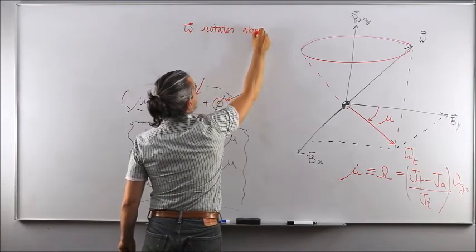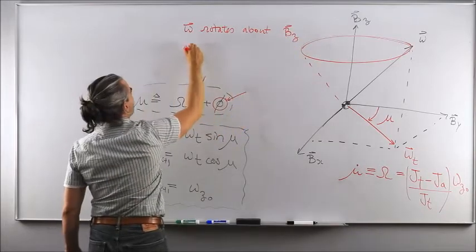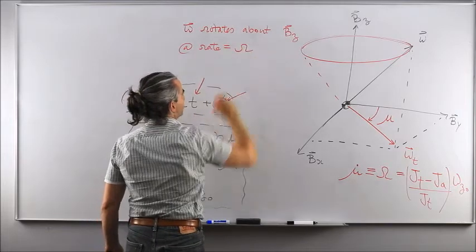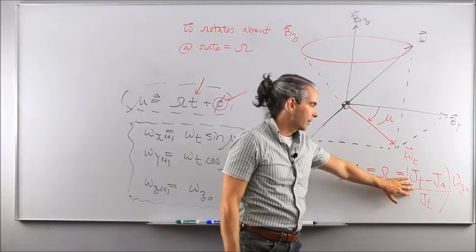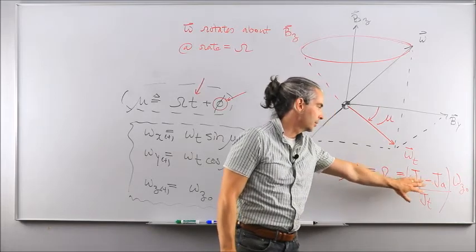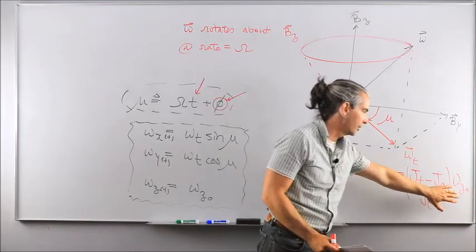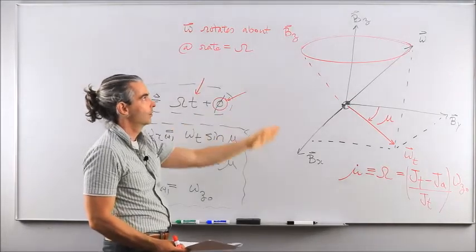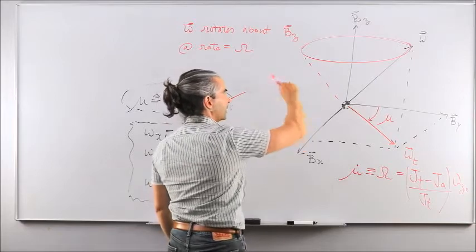rotates about bz at a rate equal to the relative spin rate. So just depending on the shear geometry of your spacecraft, quantified through the transverse and the axial principal moments of inertia, or the mass distribution of the spacecraft, and the initial component of the omega vector along BZ, we're going to get a swinging motion of the angular velocity vector like that around BZ.